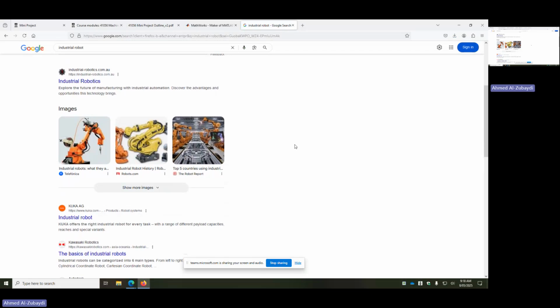Because once again, they're using the same system. They're always braked, and to make them move, you release the brake at the same time the motor starts working, so the motor takes the load. When you take your hands off, the motor stops and the brake is engaged immediately. So it's always engaged, and to move it, you have to disengage it. Now you learned something in this class. You can go out after one hour and tell everybody how this works.